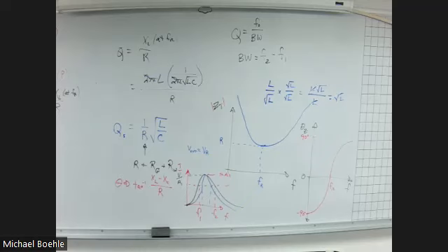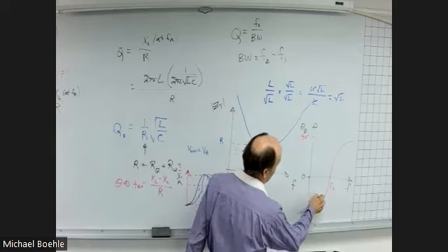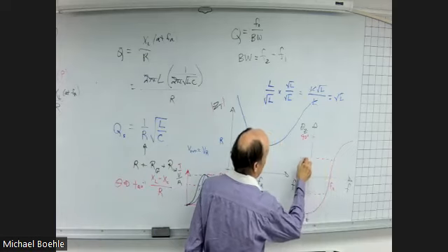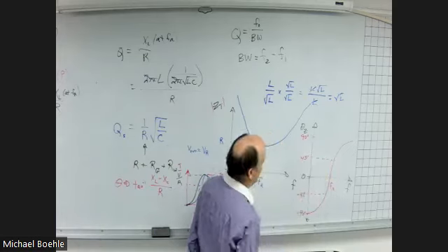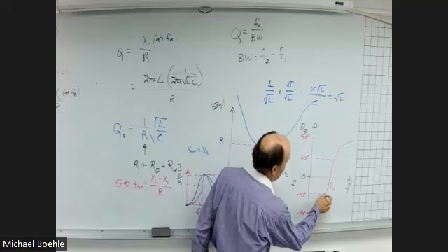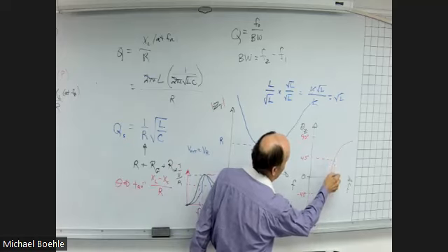I called it the 45-degree frequency. Why 45? Well, because it's exactly between 0 and 90, or 0 and minus 90, depending on which one it is, and whether you're working at impedance or current. Well, the same thing happens here. I will have a point where I have a minus 45-degree angle and a plus 45-degree angle of my impedance. Any guesses what those corresponding frequencies are?